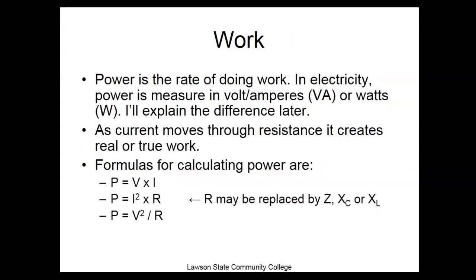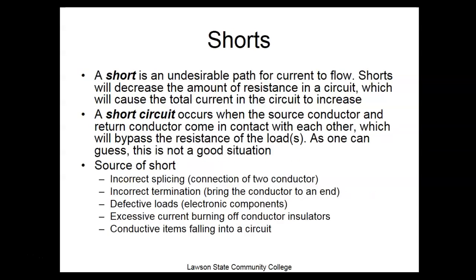I guarantee you. So we looked at work a little bit. Shorts are very important to understand when you wire these PLCs, how you hook them. What's nice about a PLC is that when you make a mistake like a short in your program, or you make an open, you're not going to cause things to happen. A short is an undesirable path for current flow. It means you still have current flow. It just means your control device is not controlling the flow anymore.